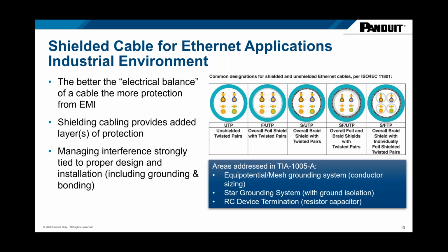We also want to look at what are the sources of noise? Where is this noise coming from? And what types of noise do we have to deal with, right? It might be internal to the cable with the conductors, and it might also be external noise, high frequency noise that we're trying to drain off of that cable as well. So from a shielding perspective, we're dealing with trying to understand those noise sources and have a defense in depth strategy to help mitigate them.